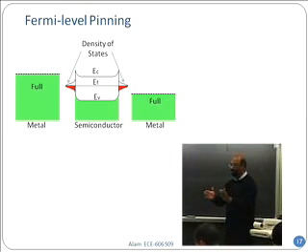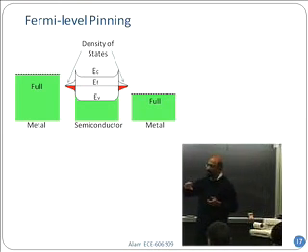When you terminate a semiconductor, make it finite, do you not have a lot of interface states? Do you remember the surface recombination velocity and all those states sitting in the mid gap and the recombination that we talked about? Of course, those are all there. Simply because I haven't drawn it doesn't mean they do not exist. And so near the edge of any semiconductor, there are a lot of surface states, as if you have this NT, the number of traps, right?